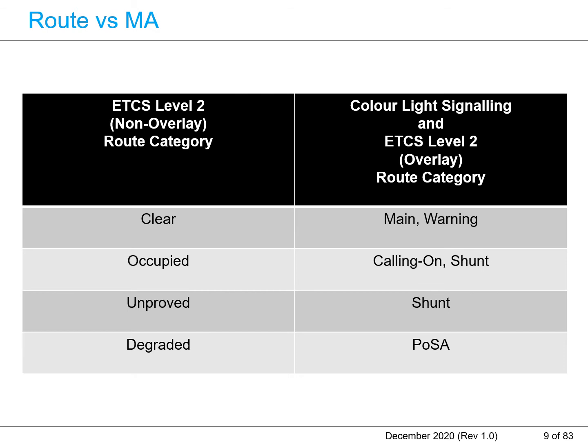The interlocking system for ETCS Level 2 does not require unrestricted overlap, or restricted overlap, for the destination safety margin purpose. The onboard ETCS in full supervision mode supervises and controls the train speed towards the location of the destination, regardless of the type or the length of the overlap section. The physical front end of the train, in full supervision mode, would not be near the block section destination, due to the confidence interval limitation. In ETCS Level 2 full supervision, the overlap is for the release speed operation purpose.